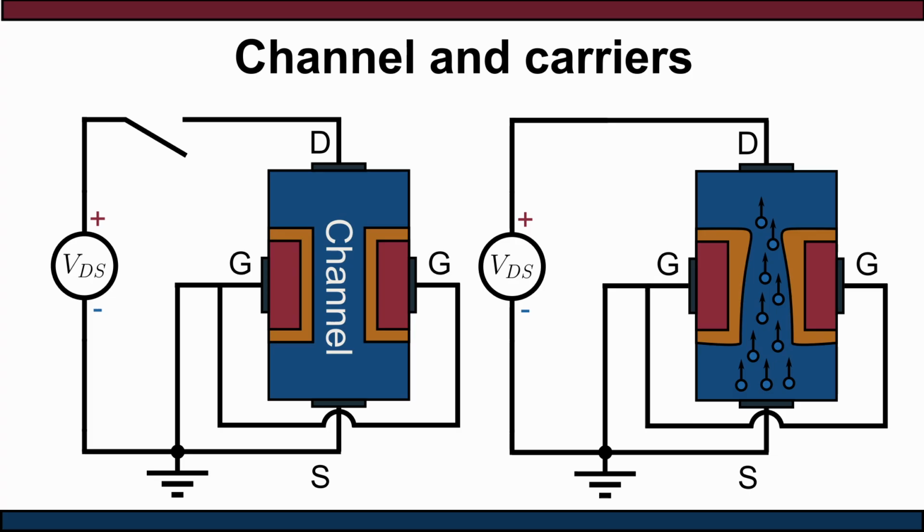How does the JFET provide this important effect? Consider what's going on in the shown semiconductor structure. If we apply voltage to the drain and source and the gate is grounded, charge can flow through the region between the gate areas named a channel. In our case, this is electrons, and we have an n-type channel JFET. There are p-type FETs, where the channel has hole conductivity.